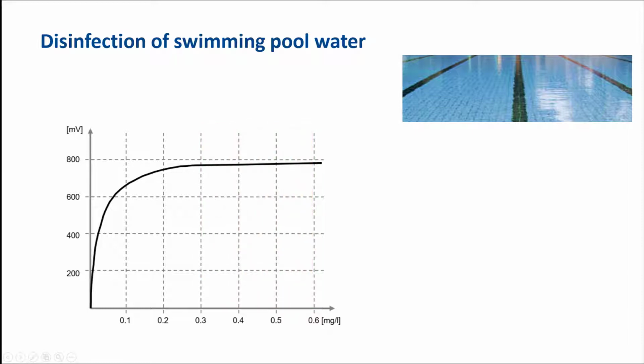Possible pollution in the bath water has a reducing effect. It lowers the redox voltage. If the redox voltage is too low, this indicates contamination and the disinfection process is not effective. In this case, countermeasures must be taken, such as a partial water change and cleaning of the filter systems.